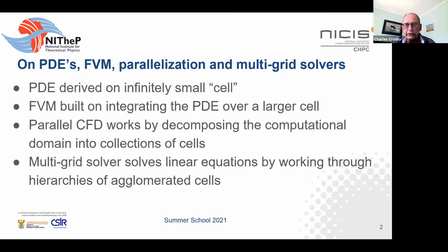So when you are completely focused on keeping the method conservative, then integrating all those volumes over each individual cell and maintaining conservation in each cell is a very effective way of maintaining overall conservation in the whole system of equations. What your finite element method is doing is assuming a shape of variation through your cell, and that does not necessarily give you conservation of the properties.